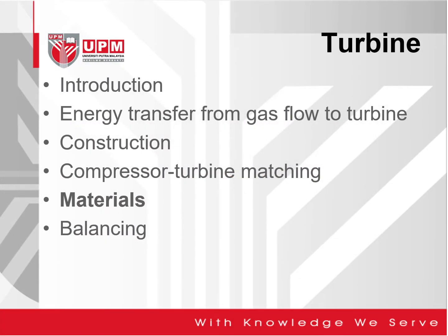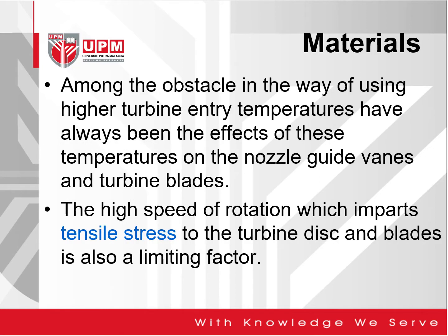Now, we look into the materials of the turbine. Among the obstacles in the way of using higher turbine entry temperatures has always been the effect of this temperature on the nozzle guide vanes and turbine blades. As we all know from our previous topic on performance, the higher the turbine inlet temperature, the higher the thrust of the gas turbine engine. So you want to have a higher inlet temperature.